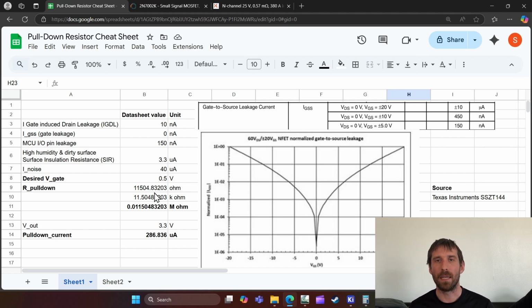I think part of this noise also is bad layout practices. They've been using 10K since the 80s. So 40 years ago, our components were nowhere near as good. Surface mount wasn't really yet. Was it even the thing back then? Doubt it. Ground planes, for what you were doing back in those days, they may not have done ground planes.